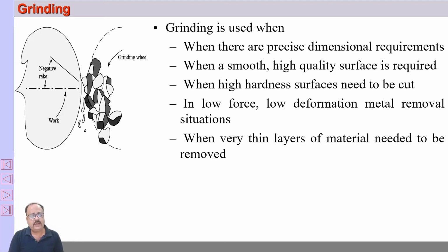Now as the abrasives are rotated against the workpiece, these abrasives become dull and fracture, resulting in new cutting edges. That is one possibility. And also sometimes the bonding material, see, abrasives are held using a bonding material in the form of a particular shape. Now this bond sometimes fractures and the abrasives are released. As a result, new abrasive surfaces with new cutting edges appear, and likewise the sharpness of the grinding wheel is maintained.